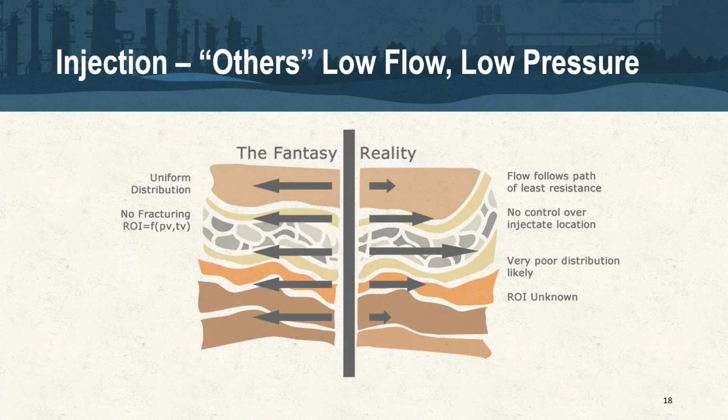A lot of times with conventional downhole equipment, you may be pumping into an open borehole. You may be trying to tremie the media into a specific interval. Even if a driller or other provider is using packers, they certainly don't have the type of pump we're discussing here today. And without that triplex pump, which I'll show you in a few minutes, it's going to be very hard to propagate your reactant into those zones and achieve distribution and treatment. So using that packer, we eliminate a lot of those drawbacks. This isn't open hole pumping. We're going to focus on narrow intervals, and we're going to make sure that we get development of that fracture feature. And if we can't force reagent into that interval, then there's a very low likelihood that a contaminant did as well.